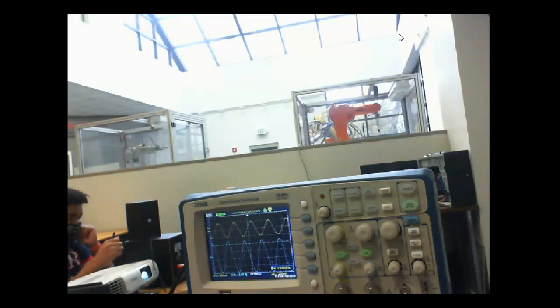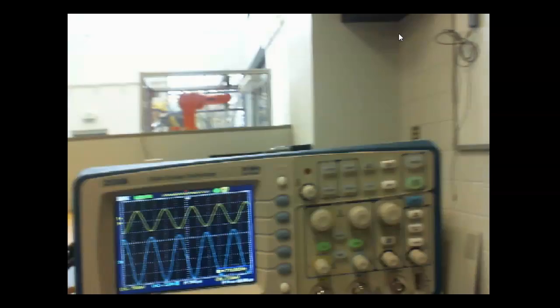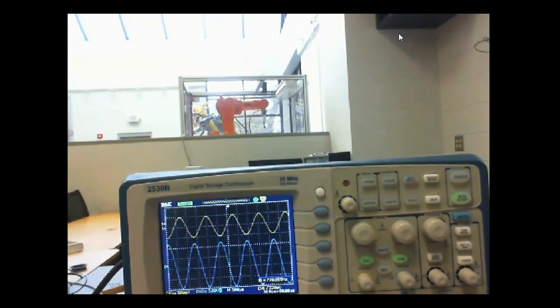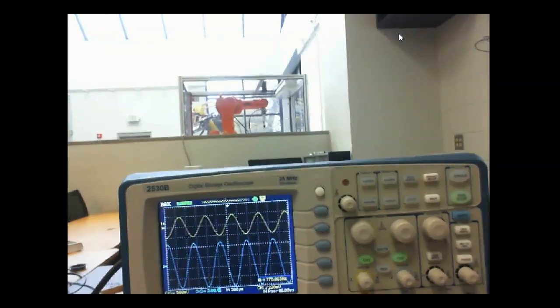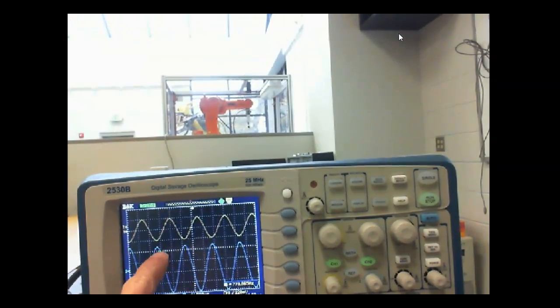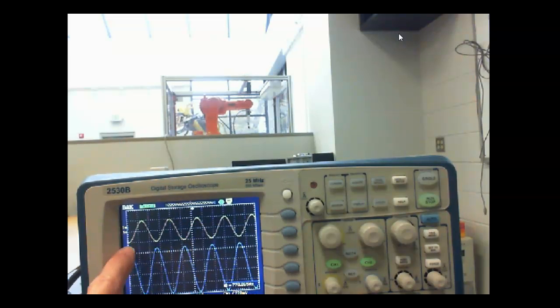But one thing you notice, if I get my camera up closer, this is a characteristic of this amplifier: when the input goes up, the transistor cuts on, so the collector voltage goes down. When the input goes down, the transistor moves toward cutoff, so the output voltage goes up. So the characteristic of this amplifier is that your input and output are what we call 180 degrees out of phase. You see that? Here's my input, here's my output. But it's an exact replica of the input. It's just that it's got gain on it, right? And it's 180 degrees out of phase.